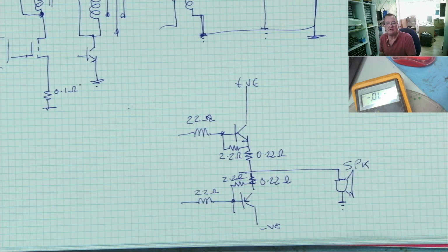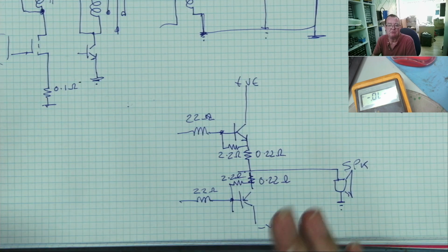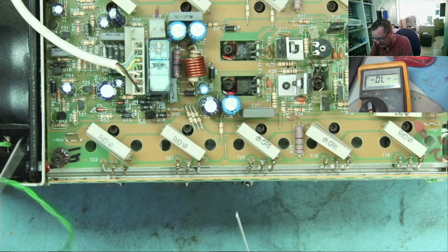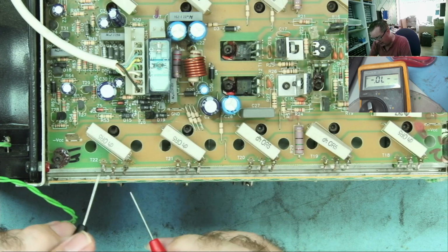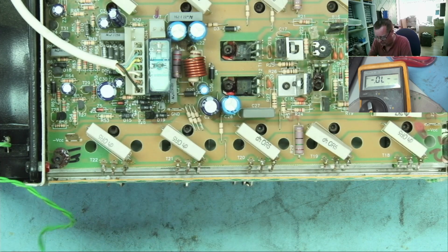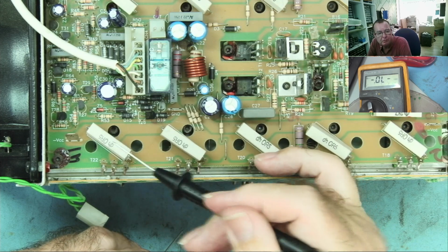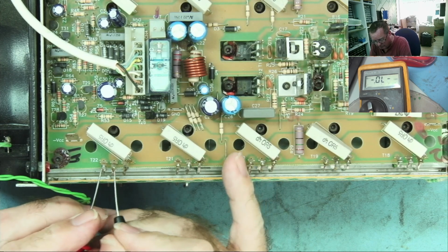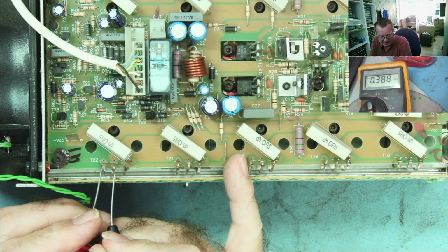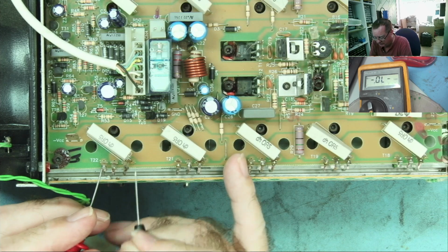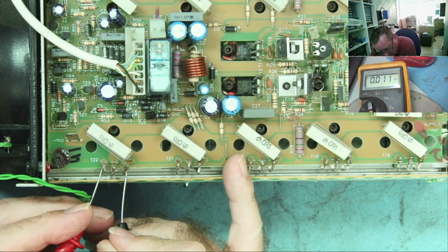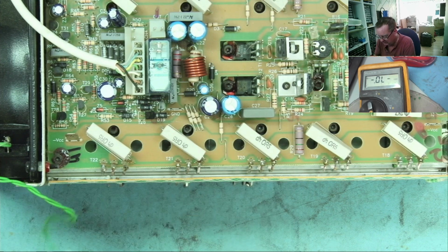Let me show you. It's easier to show you and probably makes more sense than trying to explain it. So here is a large power amplifier. These are output transistors. I think this one is the base. Let's have a look. You can see the emitter resistor, 0.5 ohms going to ground, okay? So if we measure base collector, yes, I've got it the right way around, we see a diode junction, 0.388. That reads like a short, but it's not quite a short. Look, it says 0.011.